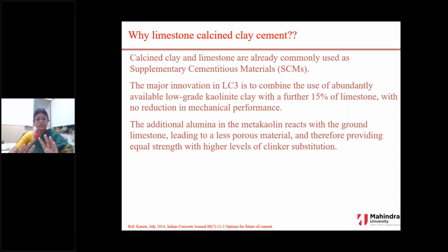Now, what is the major innovation in LC3? The major innovation is, we have seen that calcined clays were already used as a replacement for cement, but the percentage of replacement was very low during the early days. But now in LC3, the percentage replacement is very high. It talks about 50 to 60% replacement of clinker. In place of clinker, we can use the limestone and the calcined clay.